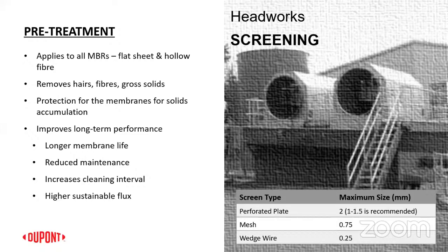A very important thing for an MBR operation or any membrane filtration is the pre-treatment. The better the pre-treatment, the better the life of your MBR. The system can handle eventualities, but continuously loading it would not be a good idea. It's like traveling on a rough road. If you have a smooth road, you can have a very good drive. If you're always going to have rough roads, you're definitely going to harm your vehicle, and you should choose a much more robust vehicle for that.